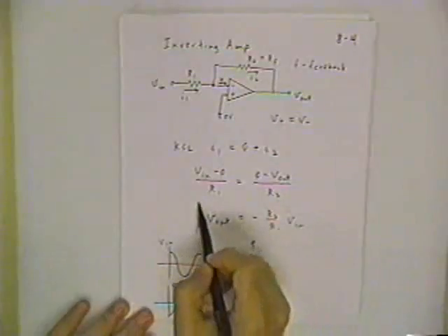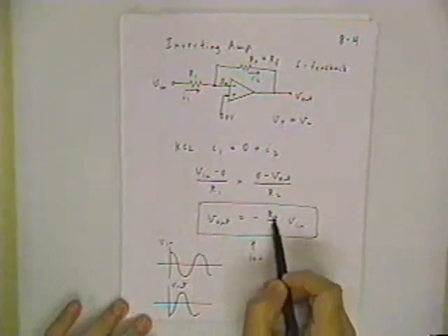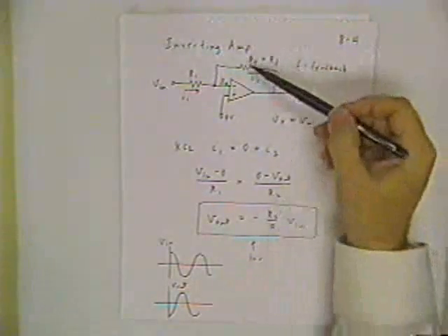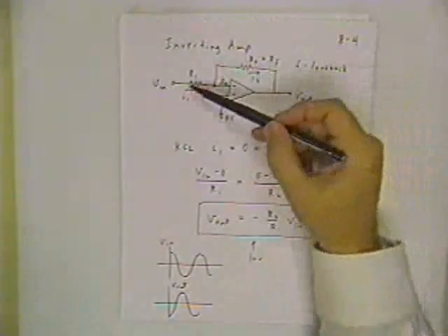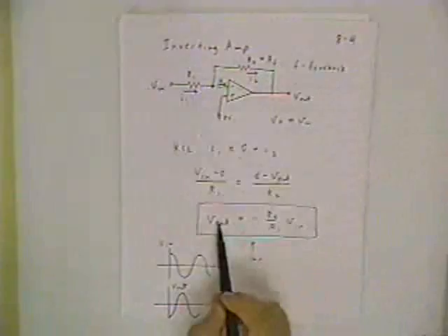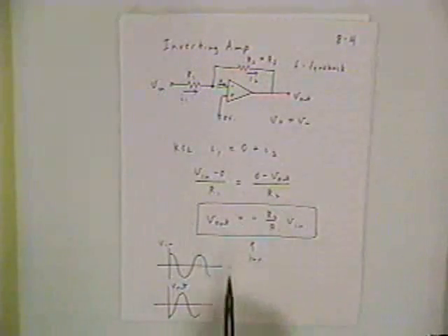That's probably, as I said, the most important thing for you to remember about the op-amp circuit, because what we can also do is substitute impedances for resistances, and we can have RLC combinations here, and to figure out the output versus input, you just make these phasors, and make these impedances and use the same basic layout.